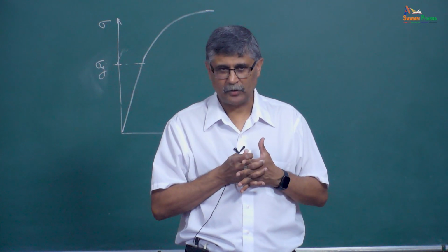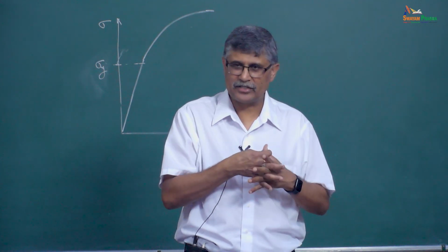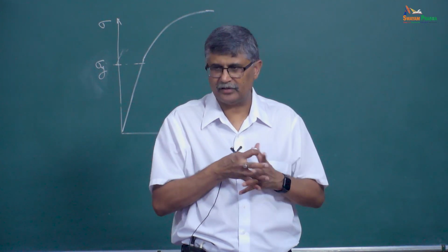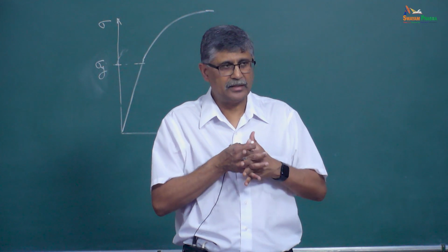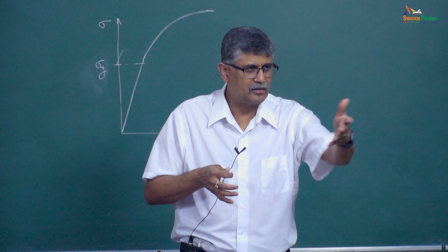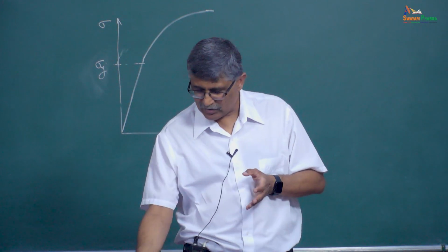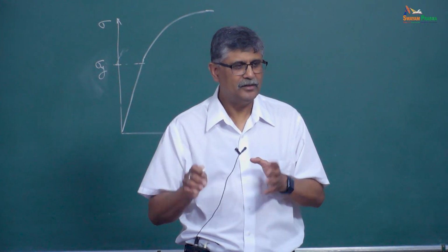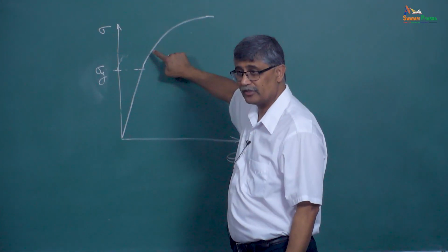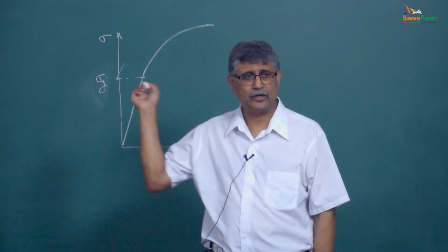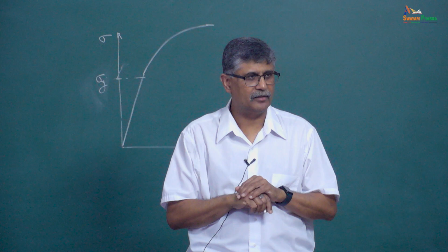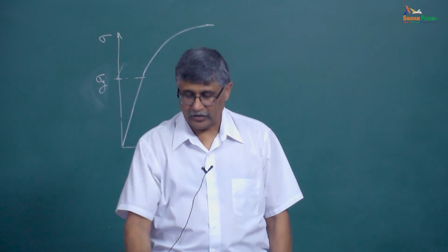But these dislocations, there could be many of them, and they could each interact with each other, okay? One can collide against the other, and so strengthening is occurring because these defects are moving in different directions, and they interact with each other. So it takes more and more effort for me to cause that dislocation to get past the obstacle, okay? So this is dislocation-obstacle interaction. That's what is happening inside the material that is responsible for this behavior, okay? That's why you see that in a stress-strain curve, but inside the material, that is what is happening, okay?